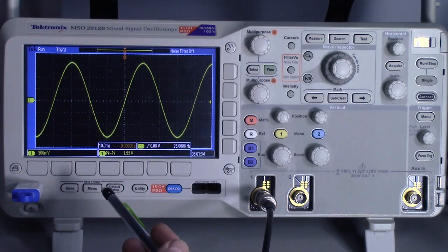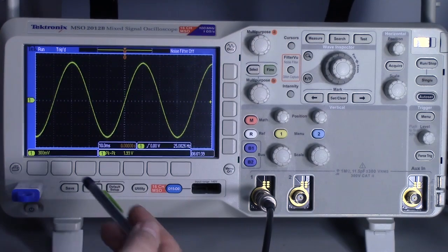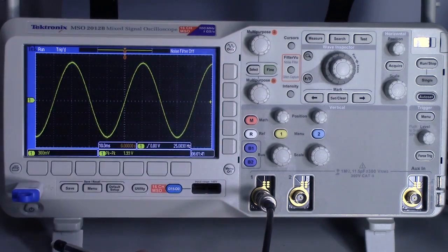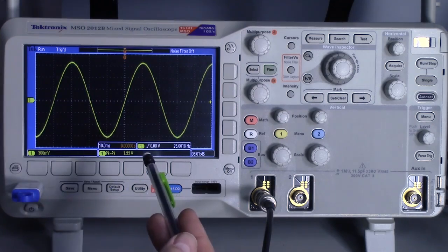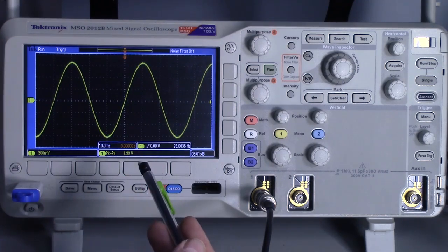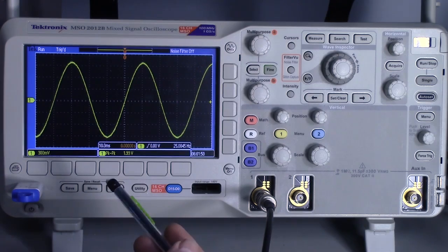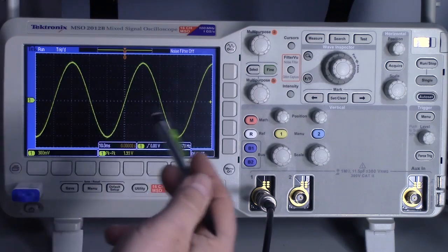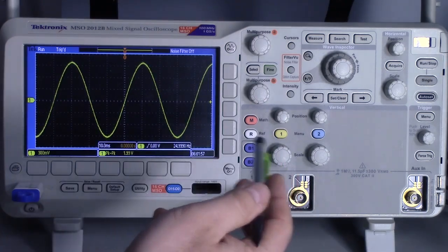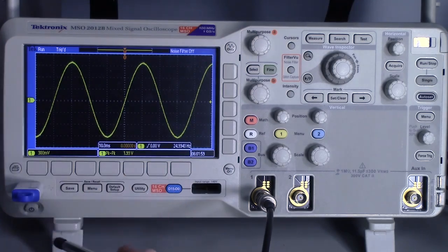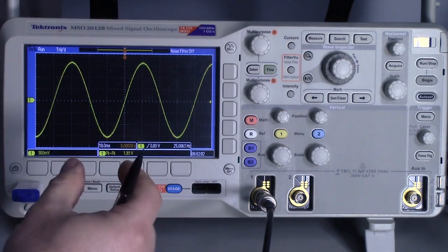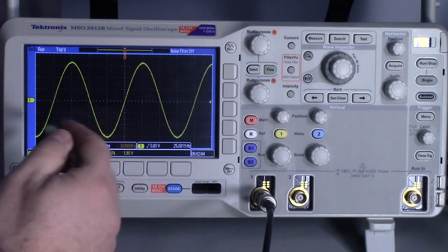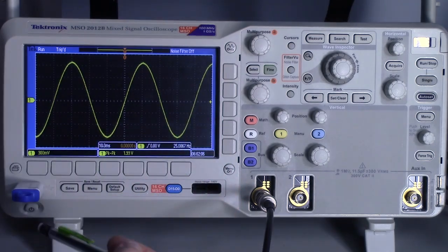Another thing that the oscilloscope excels at is gathering small pulses of data, or things that are not recurring waveforms. They're not repeating waveforms. For example, an I2C data bus is normally whatever your VCC is, either 5 volts or 3.3. And when it sends data, it's going to send it over in short packets. So it's a non-repeating waveform. We can use the oscilloscope to gather that brief packet of information, and then we can examine it, look at it, and measure it.